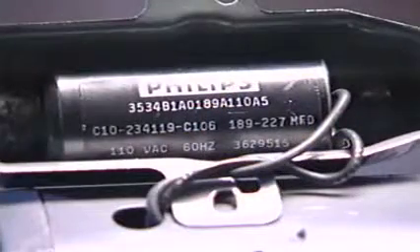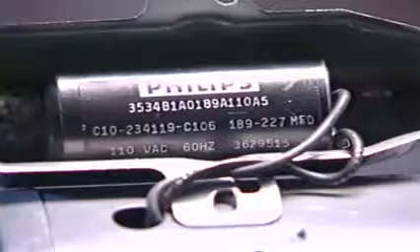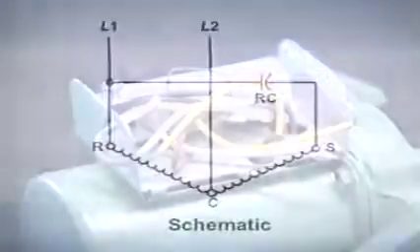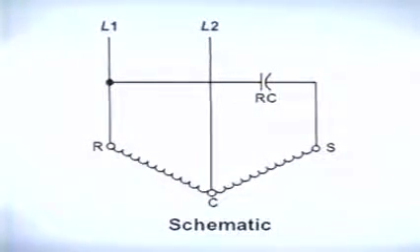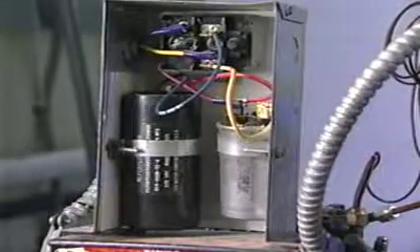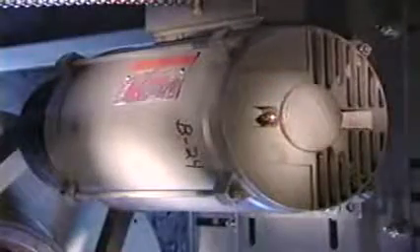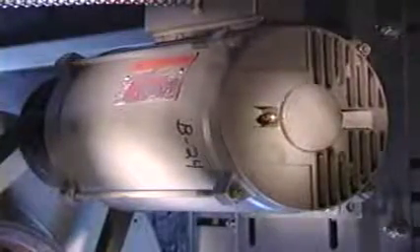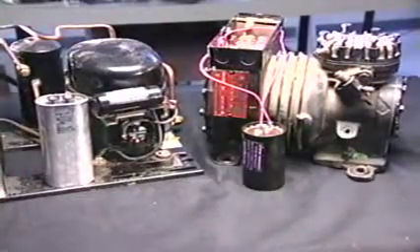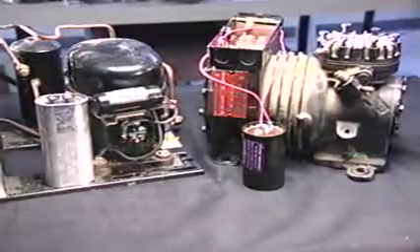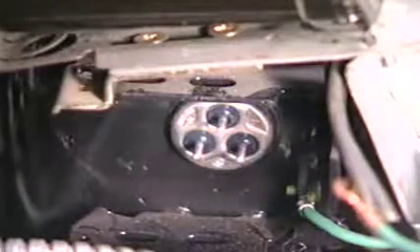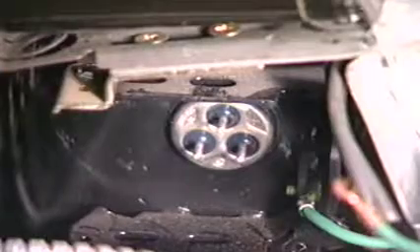Some motors use starting capacitors to increase the amount of starting torque. Permanent split capacitor, or PSC motors, use a running capacitor to improve running efficiency by keeping the start winding in the circuit. Some motors use both a running and starting capacitor. 3-phase motors have an extremely high starting torque and excellent running efficiency. Motors found in hermetic compressors can be split-phase, capacitor start, capacitor run, or 3-phase. Using an ohm meter to take resistance readings of the windings can identify the terminals on a single-phase hermetic compressor.